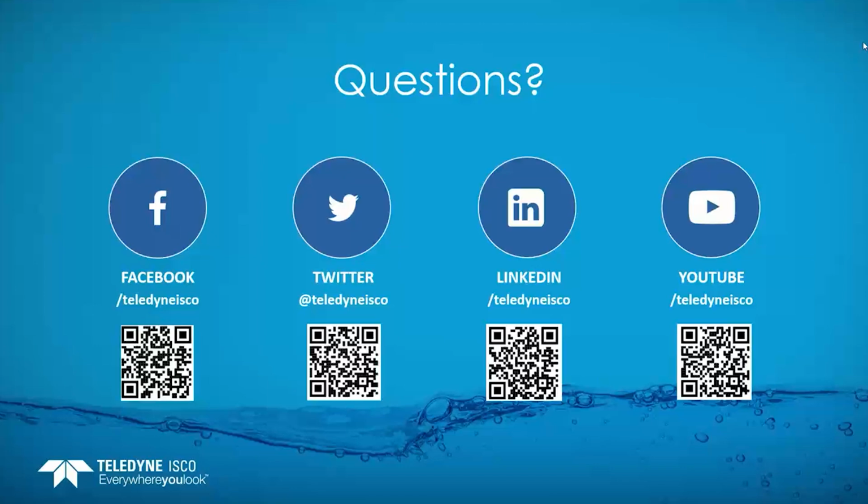Yes, there are. Here's another question. I'm assuming this is in regards to sensors. What are my options if installing in a manhole? So it's kind of a two-part answer. If it's a manhole application, you can use an area velocity sensor such as the Laser Flow sensor or our 350 intrinsically safe area velocity sensor. If it's just an open channel, round pipe, or rectangular channel with an opening, we can slide that in there. But I believe Andrew has some flume options as well.